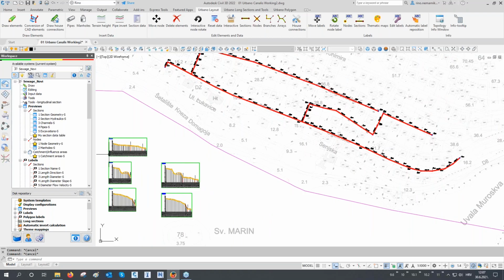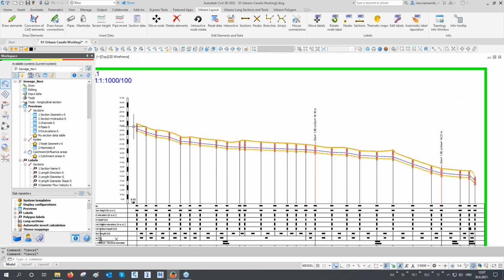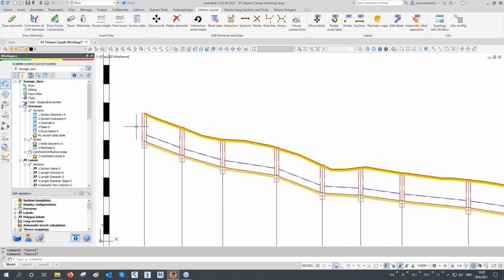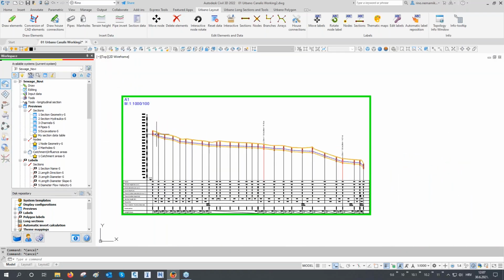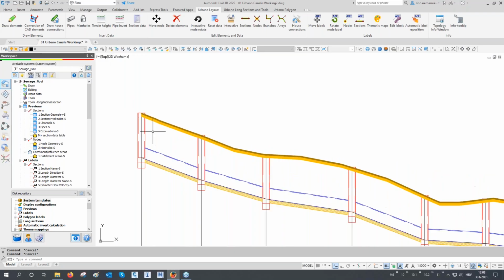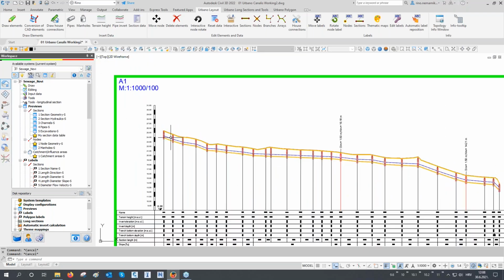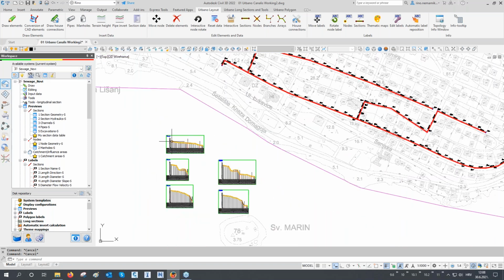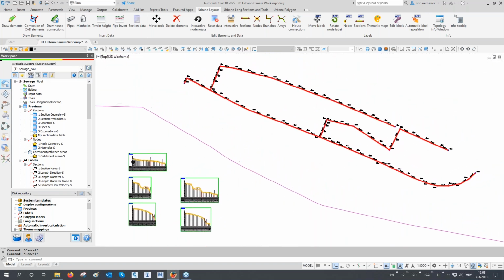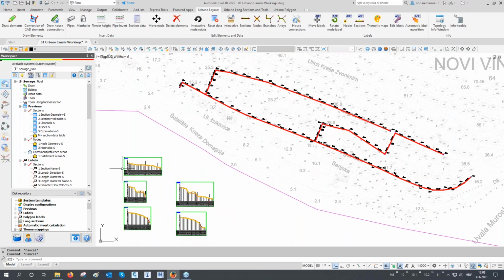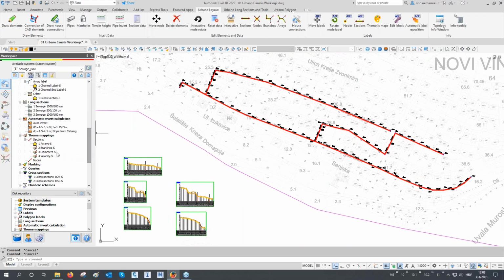I showed you how to draw profile and precisely define pipe elevations or pipe invert elevations directly in profiles. I showed you how to assign pipes and manholes from the catalog, also how to define trenches, draw cross sections, and calculate excavation volumes.